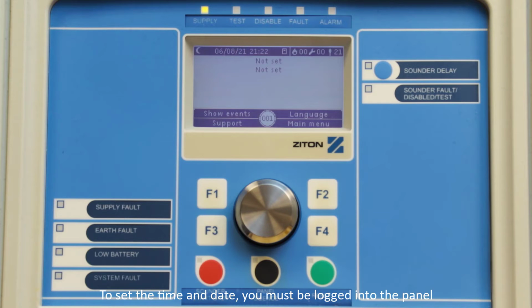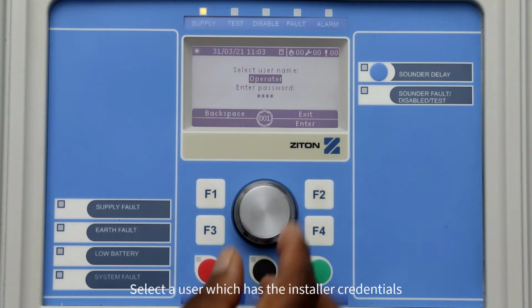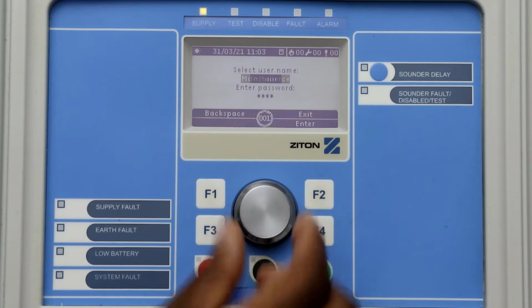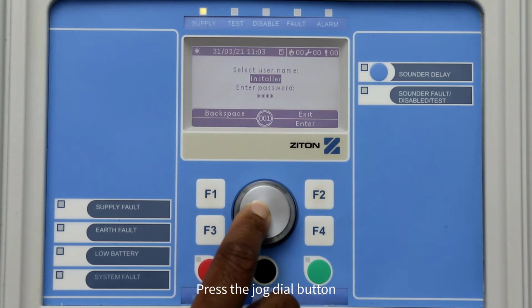To set the time and date, you must be logged into the panel, using either a maintenance or an installation code. For this example, we will use an installer code. To log into the panel as an installer, press F4 to select the main menu. Using the jog dial button, turn the dial and select a user which has the installer credentials. Now press the jog dial button to scroll down to the password option.